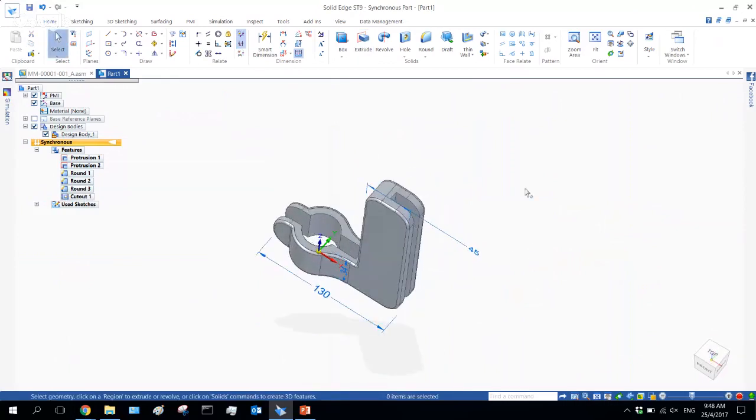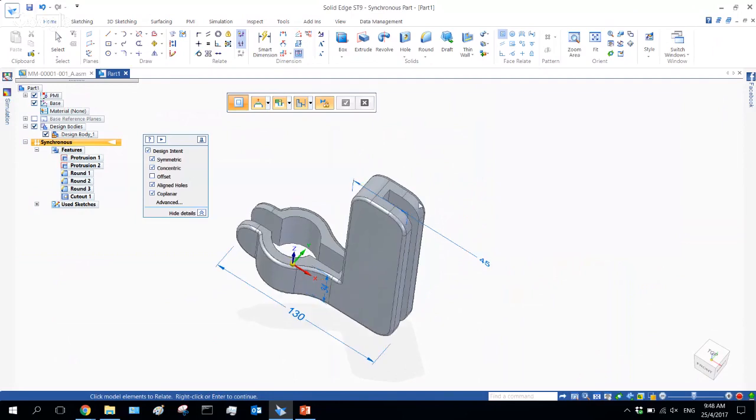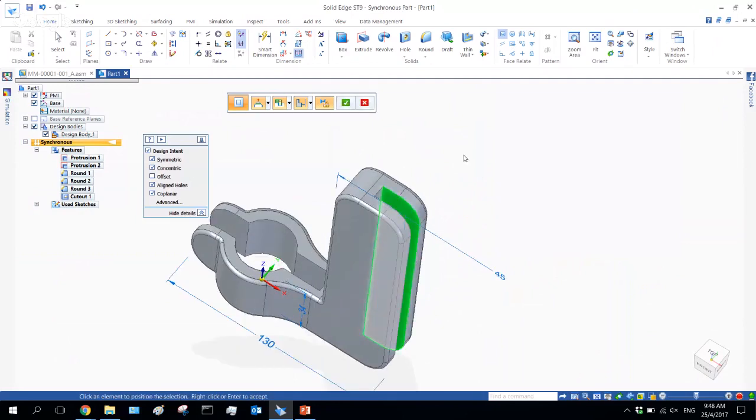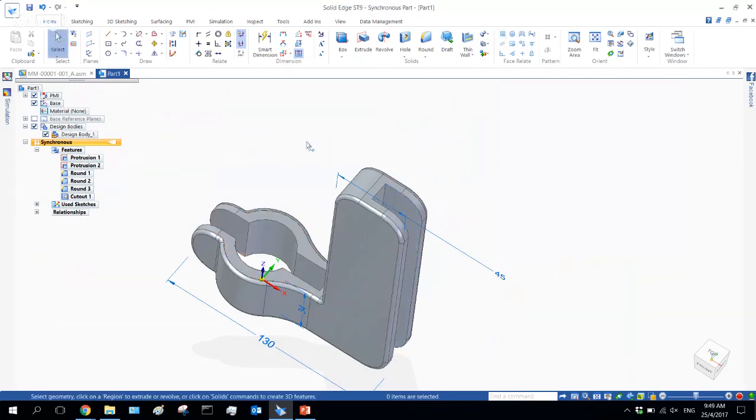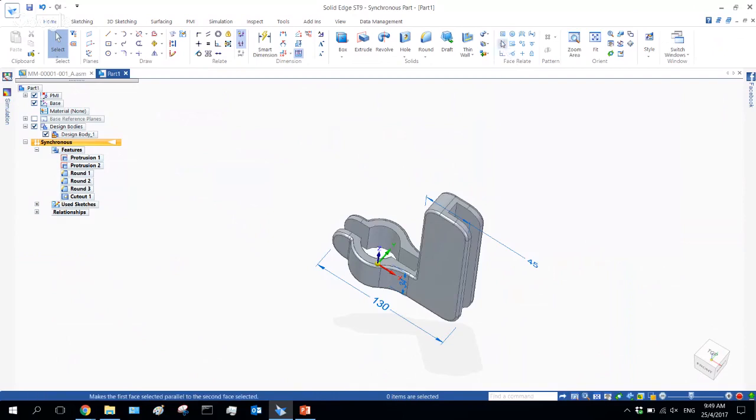And after that, as I said, we can do the relationship in 3D. So how to do it? You go to Face Relate over here, and you see the coplanar relationship. Just click it and make it symmetric. The first plane should be symmetrical, coplanar with this. I will show you the result after this. What will happen when we insert the 3D face relate of coplanar?